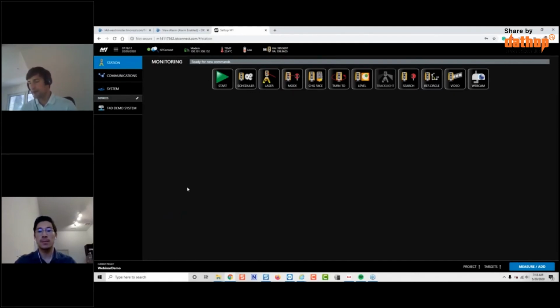And there was another question from Martin, if we also support least square adjustment. The answer is yes, T4D supports least square adjustment. So you can imagine if you combine multiple total stations in one processing engine, we can adjust all the measurements of every total station together in one flow. So this is fully supported.